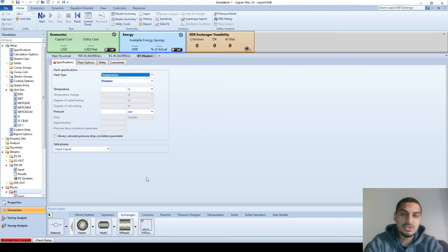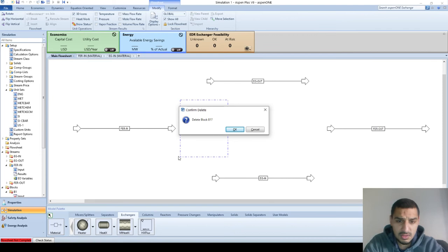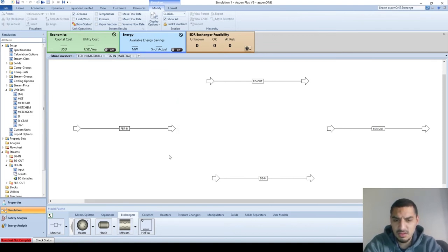The information that you need to provide is very simple. It's just the temperature and the pressure. It will give you the duty that you need to achieve this heat exchange, and that's all. That's what you're gonna get. So it's doing flash calculations. That's why it doesn't matter what the other flow is. And we're gonna use it in the next or the video after next, because there is one detail that's nice to know about Aspen Plus when we deal with this.